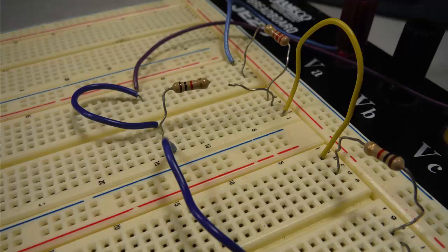If you observe no current in a series path, it's because that path is open. Case closed. Before you even think about busting out an ammeter, a voltmeter, or doing another calculation, take half a millisecond to look at your series path and see if it's connected. Current cannot flow through an open. Voltage will be dropped across the open.